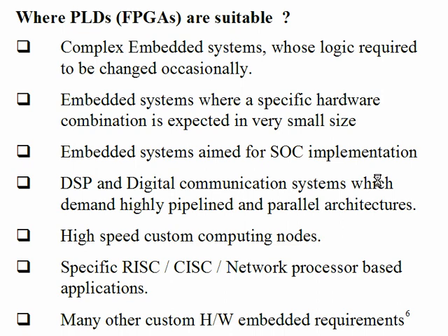That means an FPGA's capacity is equivalent to 16 processors along with the RAMs, peripheral controls, multipliers and logic cells. Logic cells can be used wherever you want to write custom logic, your own logic you want to implement. But if you require a processor there, make use of the processor inside. You got the point? Today you get FPGAs which come with DSP blocks in them. DSP blocks, what are the very popular DSP blocks?